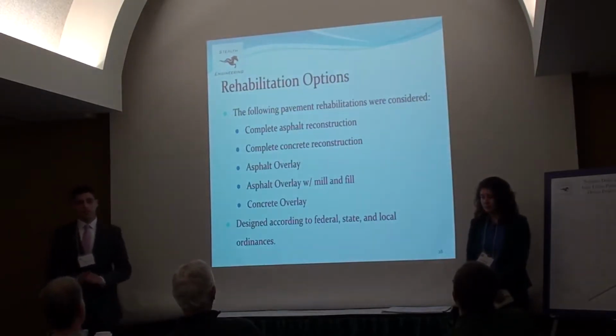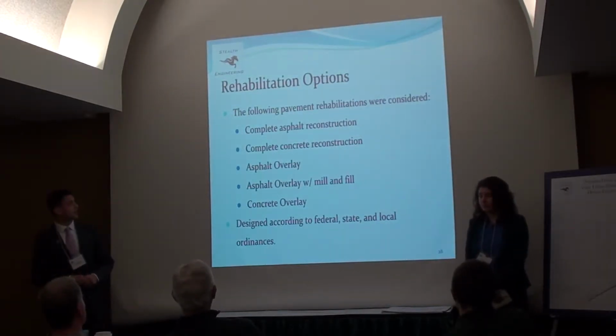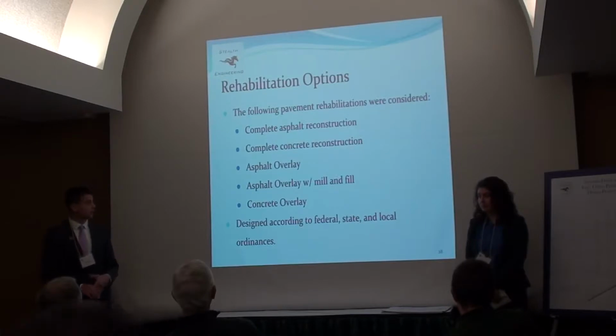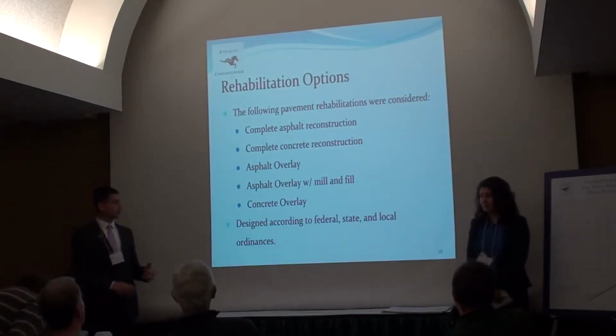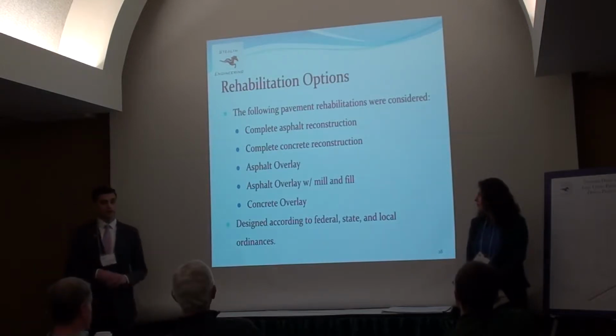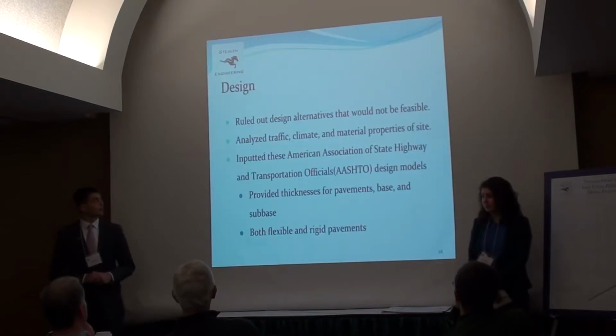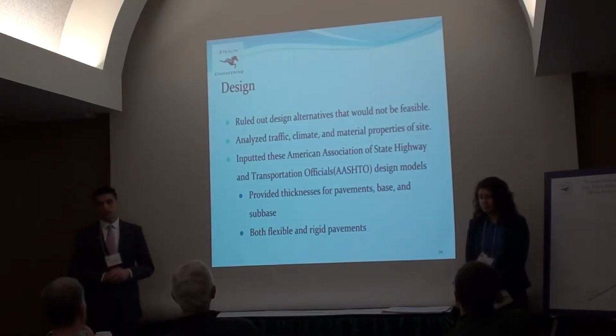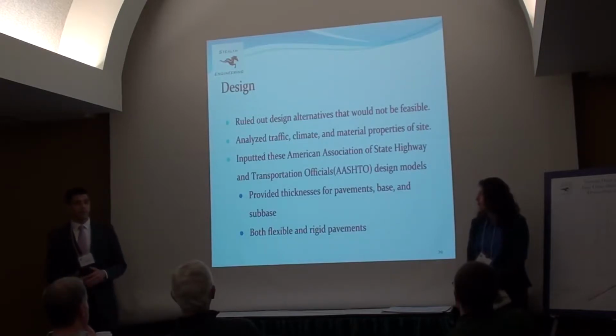The rehabilitation options considered for this project included complete asphalt and concrete reconstruction, an asphalt overlay with mill and fill, and a concrete overlay. These alternatives were designed according to federal, state, and local ordinances. The first step of our design process was to rule out alternatives that were not feasible.